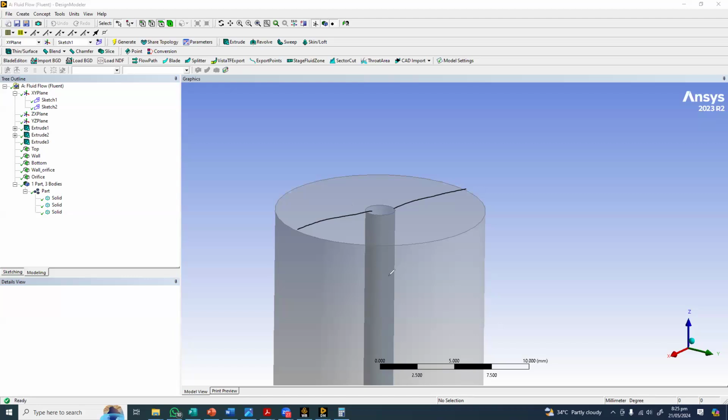And number two is that sweep meshing works in such a way that it requires one surface, which can sweep the mesh from that surface through the whole volume. Here we are not going to sweep from this boundary to the bottom, but this time we will use circular sweeping. ANSYS Meshing will create one normal vertical plane, and make the number of cells depending on what we specified here and also on the vertical edges, and this will sweep the mesh along this geometry. Because the geometry does not go up to the center, we can create the full hexa meshing very easily.